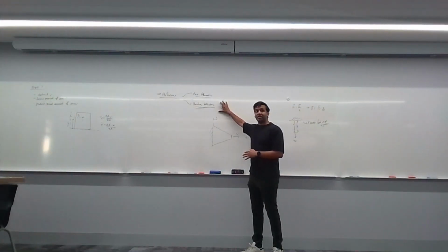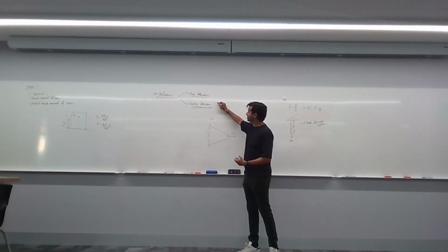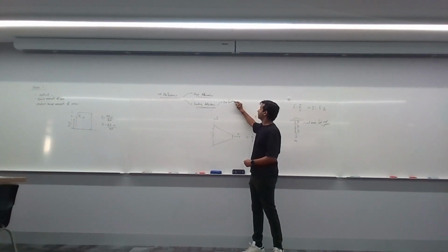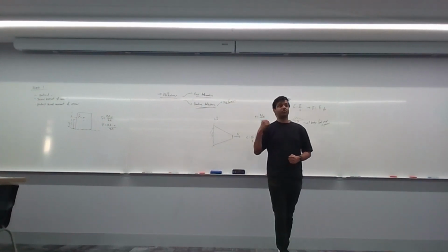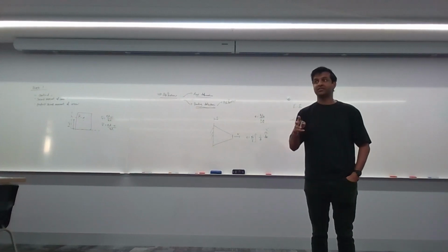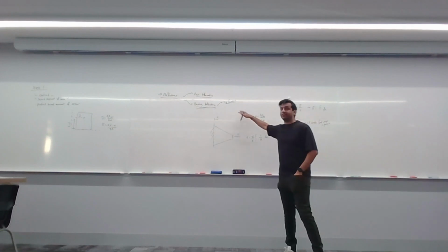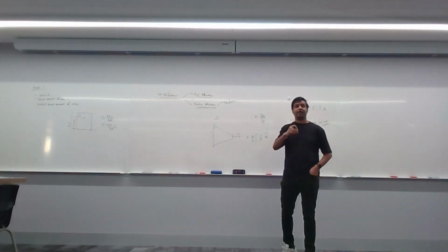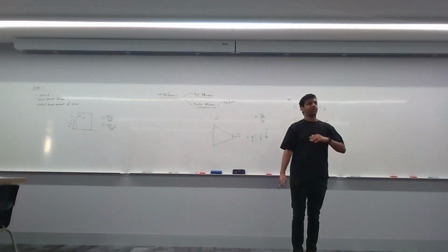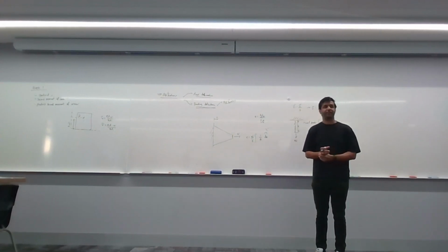And remember, in bending deflections, to me, the hardest part that you've got to train for really is your step functions. Okay, practice writing out the step functions for different structures and different shapes. Okay, and once you have your step, if you're able to correctly write out a step function for a given structure, the integration and stuff is not that hard. Okay, you'll get through that pretty fine.